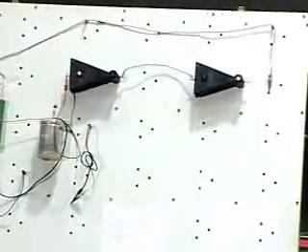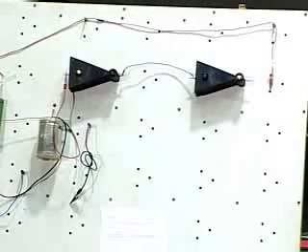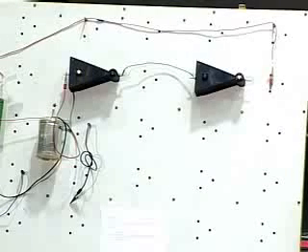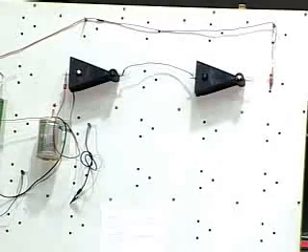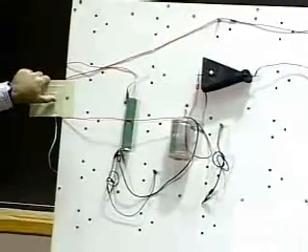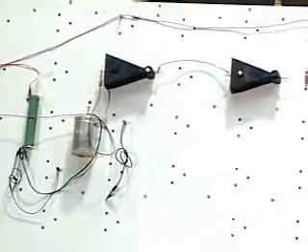Okay. And now I'm going to take the input out. As you can see, it's stored. In fact, we have to wait for a very long time. We don't have enough time to wait for this to discharge. So instead, what I'm going to do now is I'm going to add also the resistor. Okay? So now I'm going to flip the resistor in parallel with the capacitor to imitate what happens when we have an input resistance.